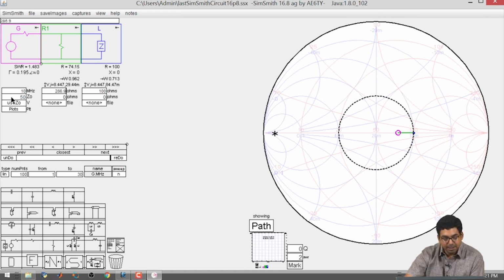As you start reducing the shunt resistance, it will go all the way to the left hand side of your Smith chart. If the conductive path here has negligible resistance, almost no current will flow through the load. That means that you would have short circuited, and the representation that is seen by the generating side here is a parallel combination of a short circuit and a load, which is a short circuit.